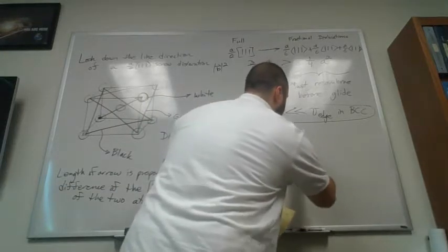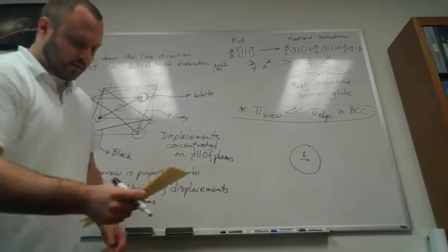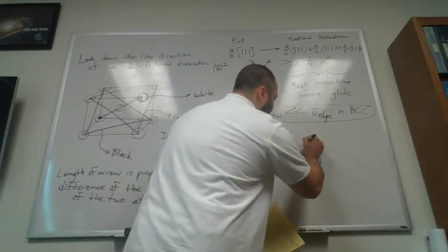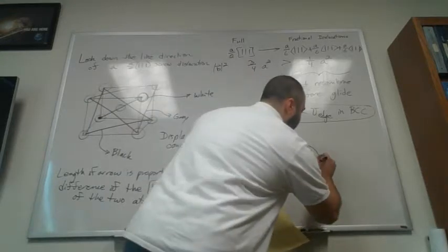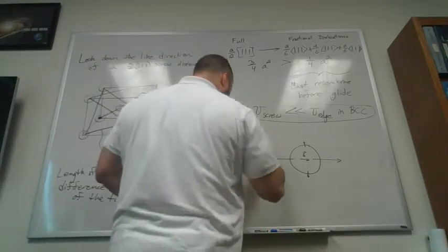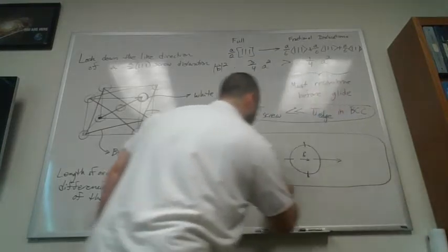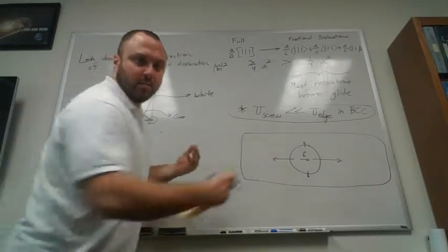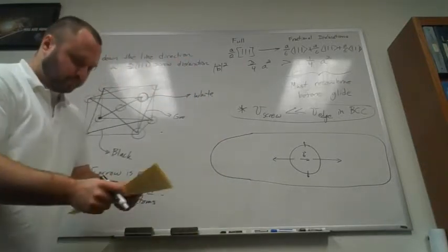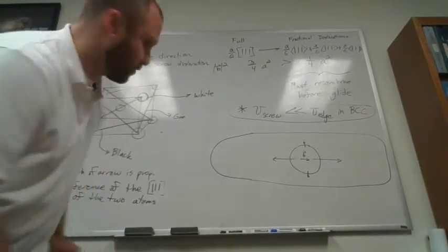Okay? So if I draw a dislocation loop, its Burgers vector was this. These ones on the top and bottom are going to be screw dislocations. They're going to have a really small velocity, which I'm going to represent with this arrow, compared to the velocity of the edge components. So if I take this thing that started out as a circle, and I look at it at some later time, I'm going to find that it's now very elongated. It hasn't moved that much up and down, but it's moved a lot right and left. And I'll even make this bigger to accentuate this. Right? It's really stretched out. So it turns out that that has a large impact on how these things even move. What's the mechanism through which they move?